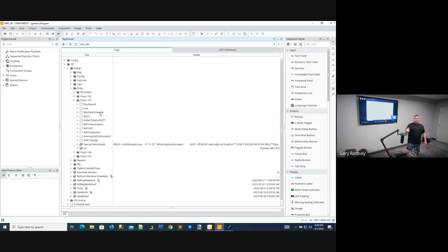Semantic hierarchy is if I taught you a hierarchy for data, and I said we have structured all the data in our business a certain way. And this way we use ISA 95. So enterprise, and then go to the site, and then you can go to the area in the business, and then you can go to the production line in that area, and then you can go to the cell in that production line. And if there is something important for that cell, like a file, it's going to be right next to the cell. It's going to be under the cell. There will be an Excel spreadsheet for that cell. It's a semantic hierarchy that tells you how to get to the data you're looking for. Everything we build is like this. So when we say UNS, it's like this.